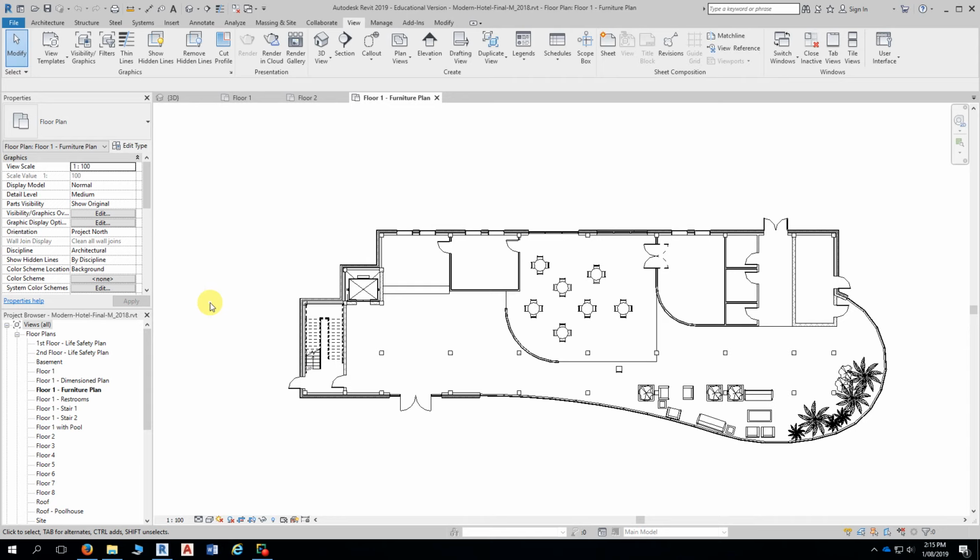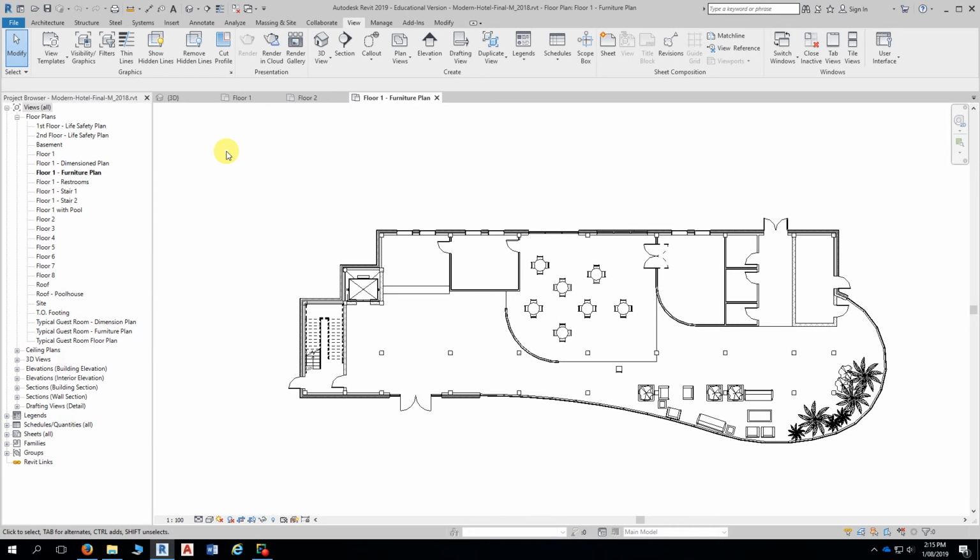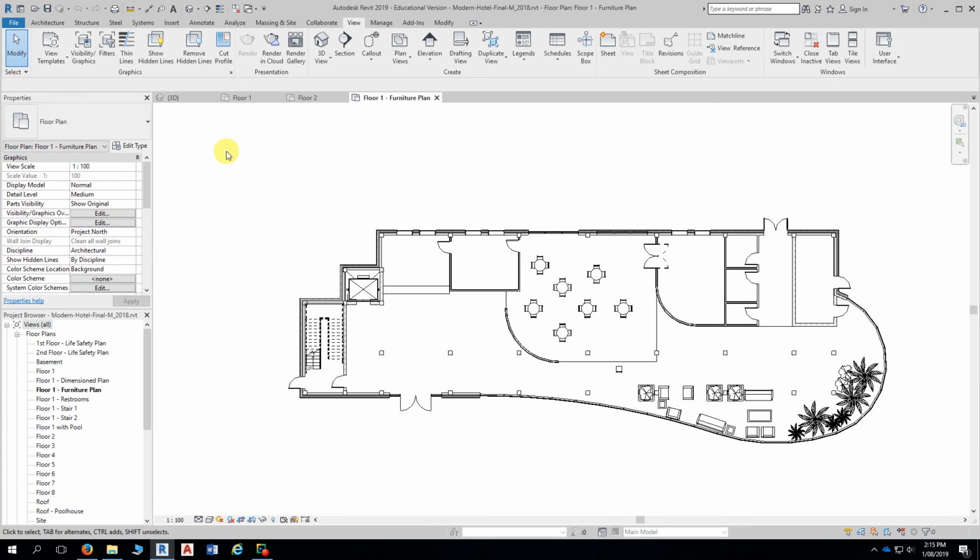I've just accidentally closed it. So the thing is now with shortcuts, for instance, if you actually lose the properties palette, the shortcut for that, remember what it was? Double P or Control key 1. So PP. Typing PP will get rid of it, typing PP will bring it back, or Control 1. I seem to have lost it all. I've made it all disappear.